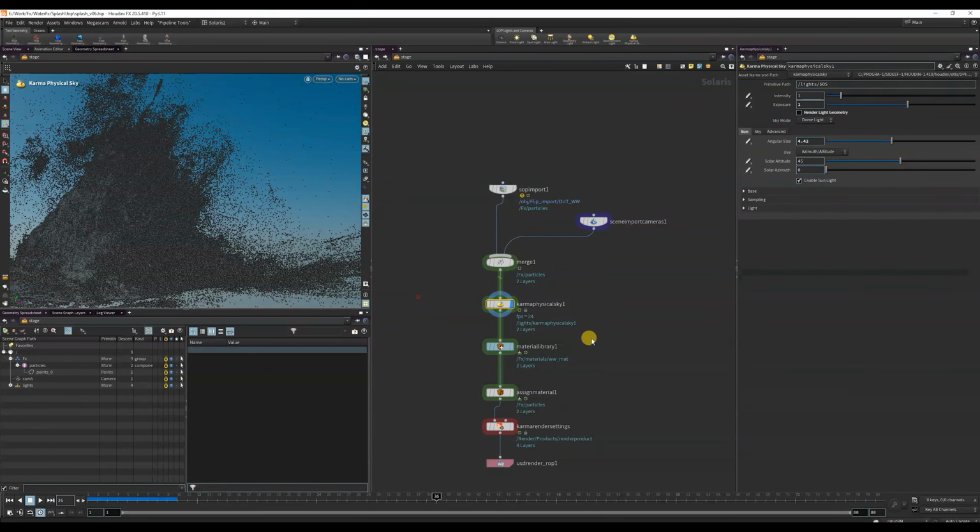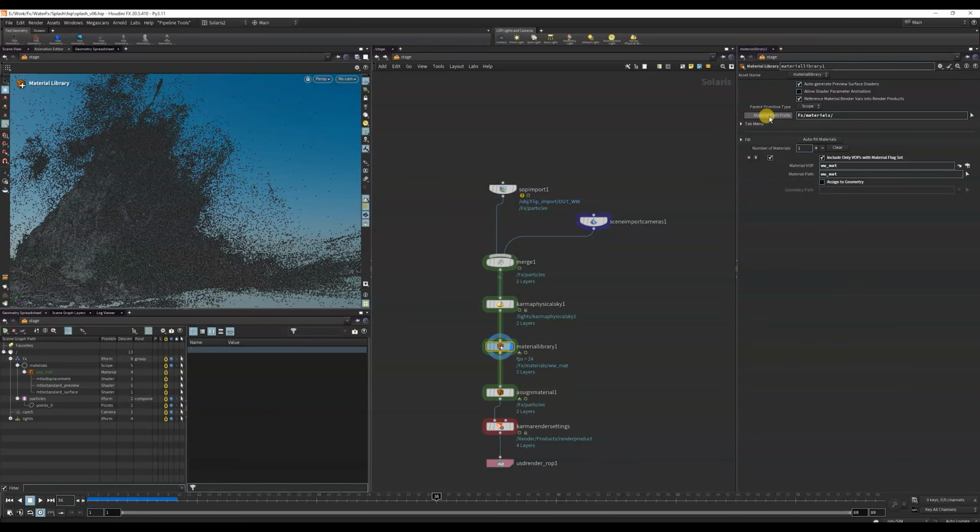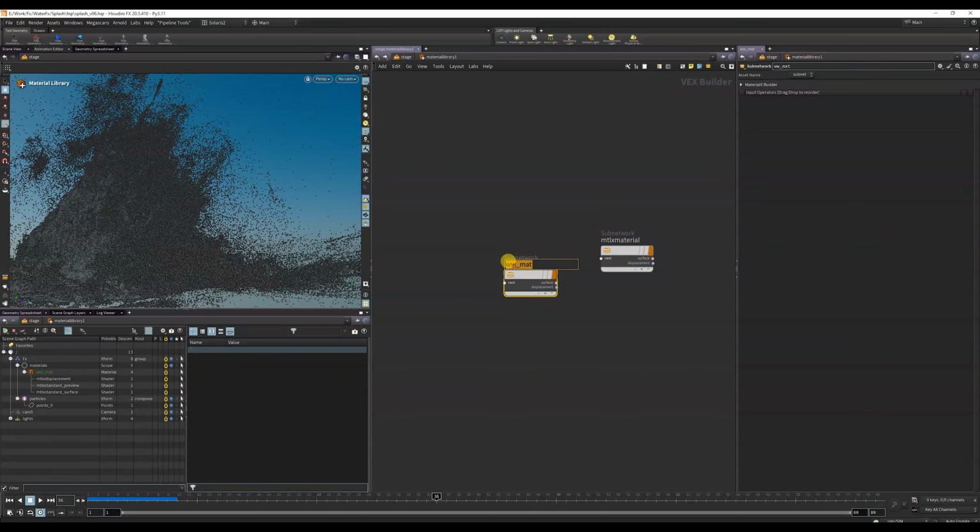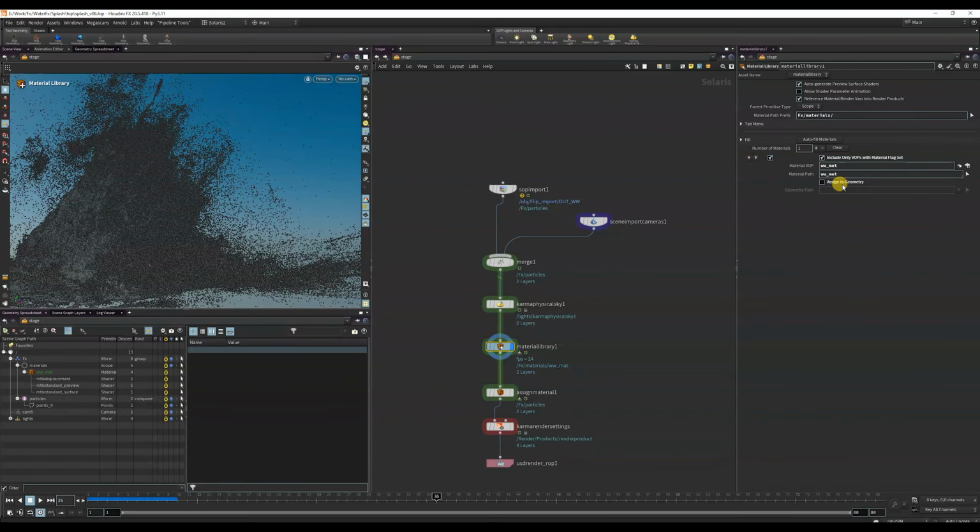I just merge these two things. Okay, and I create a material builder. The material path prefix should be the effects, and I manually type the name material. Make sure to add a slash. You can get these effects under materials, and here is the white water mat. So in the material box you can just choose white water mat. From here you can type the name white water mat, just copy this and paste white water mat.